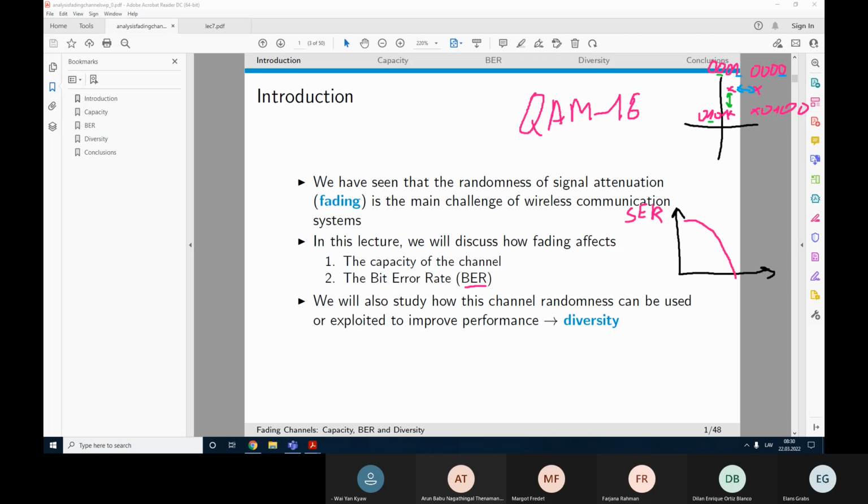And in another color, yellow, for example, here we have this difference in this bit. And finally, here the difference is in the second bit. So that was called gray mapping, and that was the reason why we used it, to avoid needless binary errors. If we have transmitted this symbol, however, because of an error in the channel, we have received this symbol, then it will translate into a single bit error.